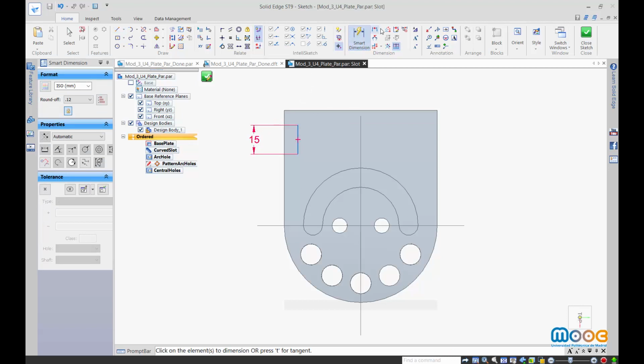Also, we are going to establish a distance with the vertical axis of 13 millimeters, with 1.5 space between a slot. We have 3 spaces, we need 13 millimeters. Also, we need to establish a dimension for the distance between the beginning of the slot and the end of the part, 8 millimeters in this case.